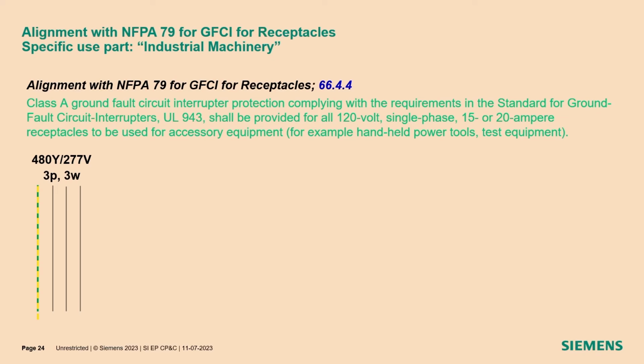A lot of people ask me, hey Max, I have no idea how to bring a receptacle into my panel. And this is why I created the slides here, because here in Germany especially, they want to have a receptacle with 240 volts. And this is definitely not possible anymore. If you go to America, we need 120 volts. You see this here in the text. So please use these types of receptacles. And this special type is also able to be put on the DIN rail. So you have a very nice option to bring this into the panel on the DIN rail. So this is perfect.